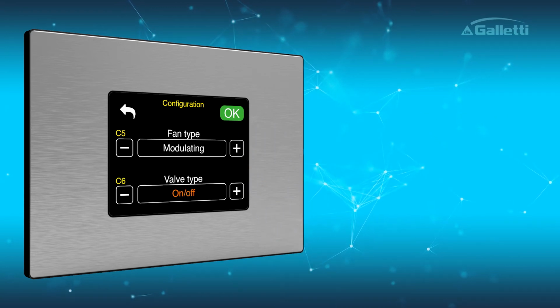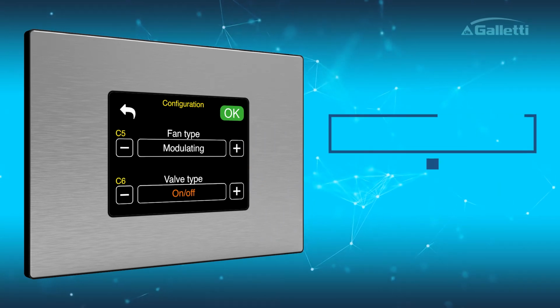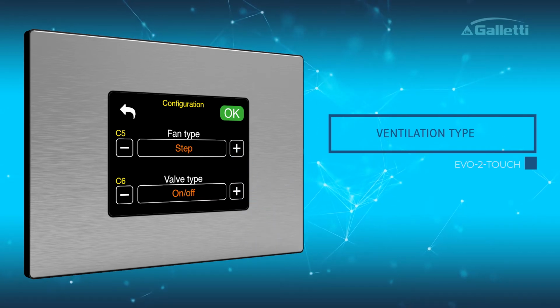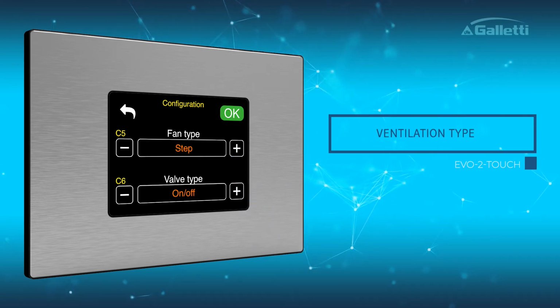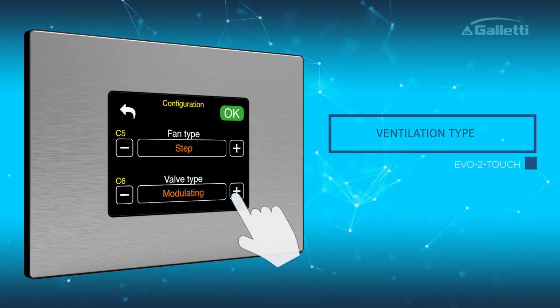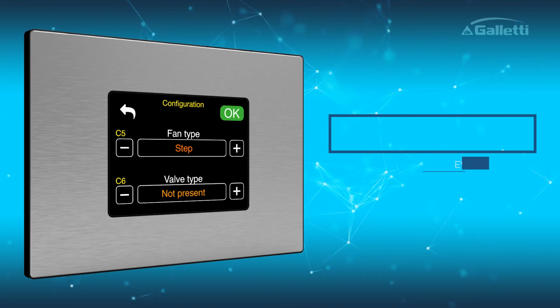On the next screen, you can set the type of fan control, choosing between modulating fan or step fan. 3 options are available for the type of valve: on-off valve, modulating valve, or none if there is no valve to control.